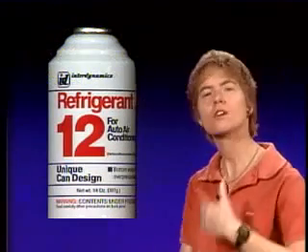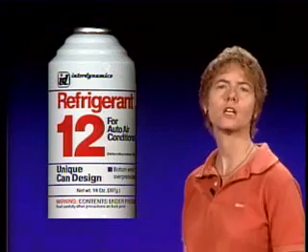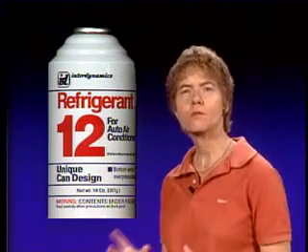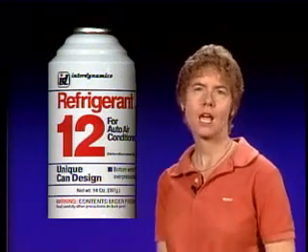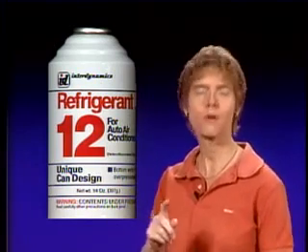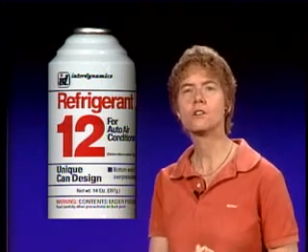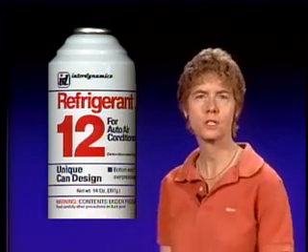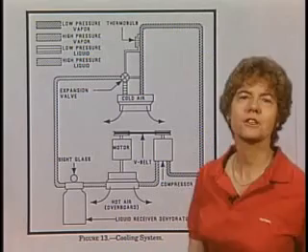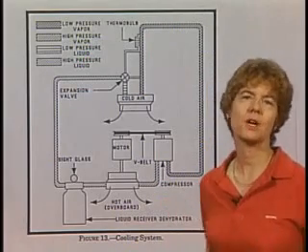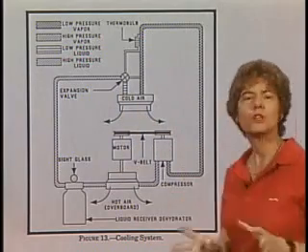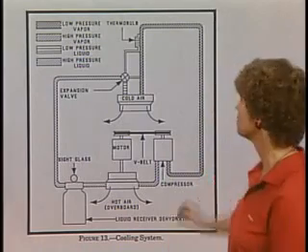First of all, the moisture can freeze in the system and basically just shut it down. And in addition to that, if you've got water in the system, it will react with the refrigerant and form hydrochloric acid. And hydrochloric acid will be very corrosive to the metal in the system. So water can both freeze and shut the system down, and it can also form hydrochloric acid, which will corrode the system. Okay, so we know why we need to evacuate a Freon air conditioning system. Now let's talk about how we do it. The way you evacuate a vapor cycle cooling system is you attach a vacuum pump to the system.